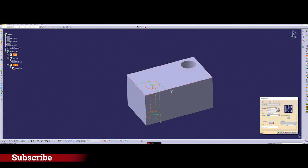So here we have more options actually for the hole. We have simple, meaning without threads. We have tapered, counterbored, countersunk, and counter-drilled. So here we can choose the counterbored or countersunk, whatever we like. Here I will leave it as it is, which is the default values. And here also we have threads.